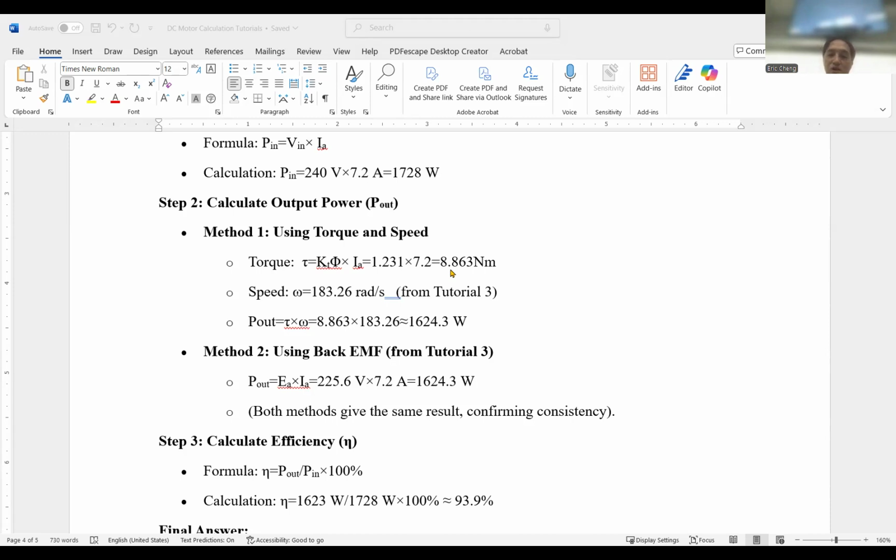The input voltage to the armature will be the VDC source multiplied by the duty ratio of 40%. This is the voltage across the chopper. It's a PWM converter, really the one we showed you, the most simple DC chopper. So 40% multiplied by 200 volt is 80 volts. The average voltage we apply to the armature will be 80 volt.